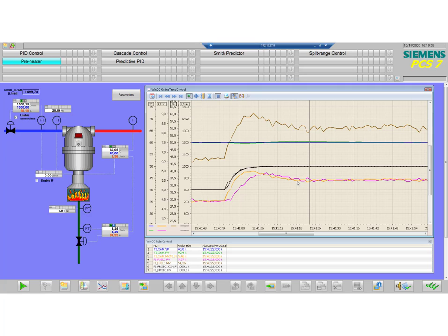We have done this in this simulation because if you use an exact feed forward, of course you would have the green line hidden below the blue line, and in reality your feed forward is never perfect. It's assisting your feedback for most of the job, but the controller has still to assist, and this is also the case in this simulation over here.